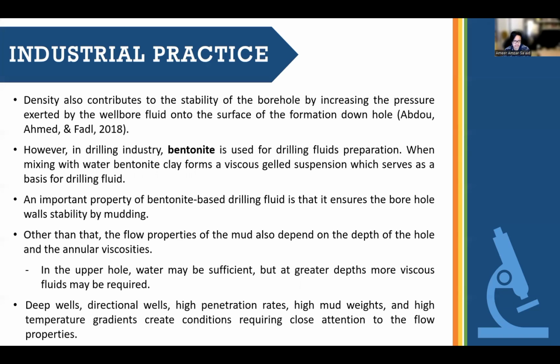When the drilling fluid circulation is stopped, the clay suspension prevents cuttings from subsidence. This prevents blockages in the borehole and, as a result, any accidents.